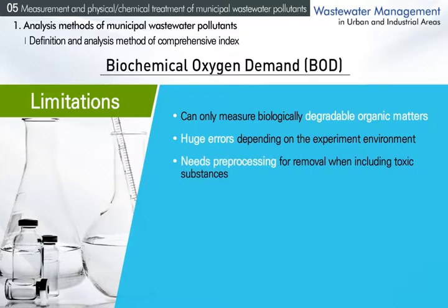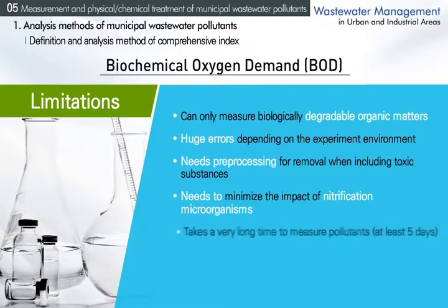Third, pre-processing is needed to eliminate toxic substances when measuring the BOD of wastewater that includes toxic pollutants, because they influence the activities of microorganisms. And fourth, an action must be taken to minimize the impact of nitrifying microorganisms. Lastly, BOD takes a very long time to measure pollutants.